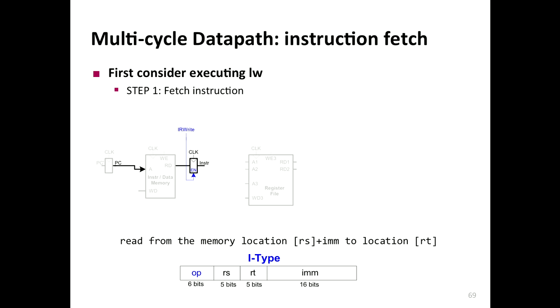So this is the first fetch instruction, right? You fetch the instruction, you input the PC over here, and you enable. This is the register that we added, basically. You produce an intermediate result. That's the fetched instruction. That's an instruction register. That's the cost we pay, right? We just added a register over here. Now your clock cycle is this short, right? But we haven't added other stages yet.